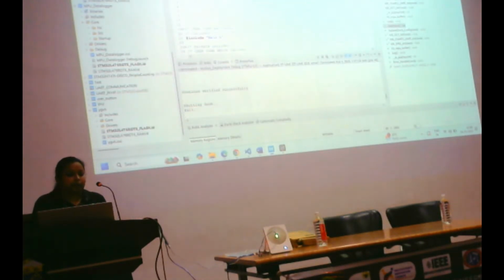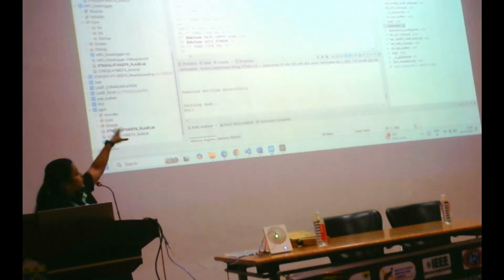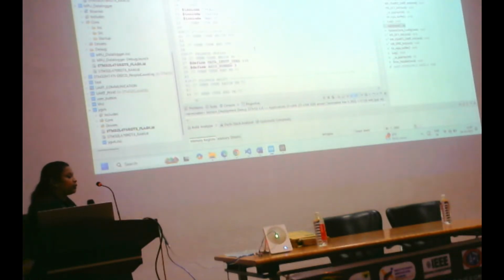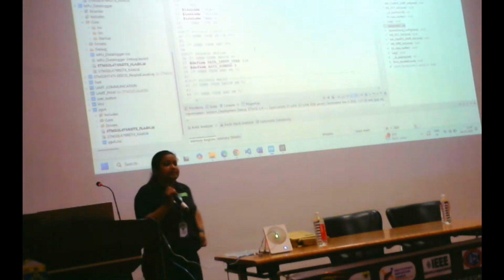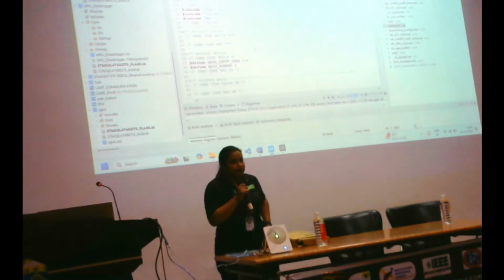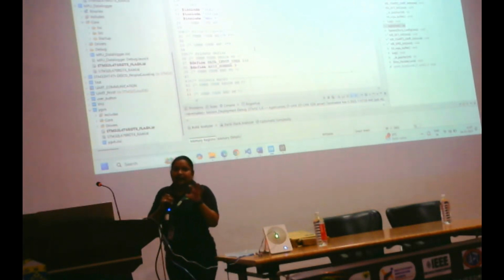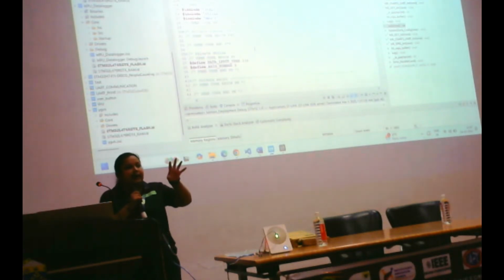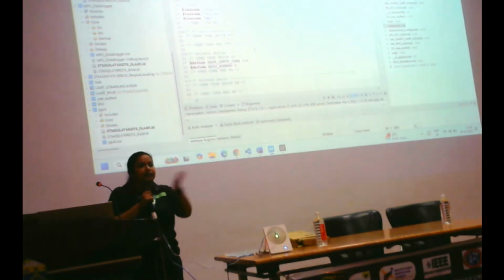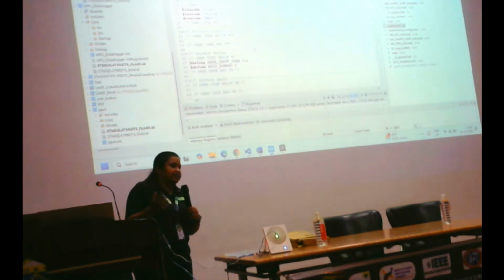So after configuration, this is the template. Here, this sensor is basically an I2C sensor because it has SDA and SCL pins. So that means I have to configure my I2C and UART communication, because through the USB cable I am communicating the data.